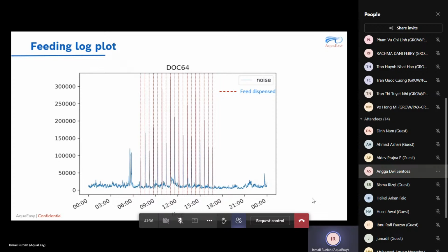The third parameter is the feed quantity we configure here. This is why we need to do the dispensary test. This also controls the feeding schedule. For example, today we plan to feed 50 kg for the whole day. If the feed quantity is 1.13 kg for one dispense, then the iFeeder will dispense roughly 44 times.